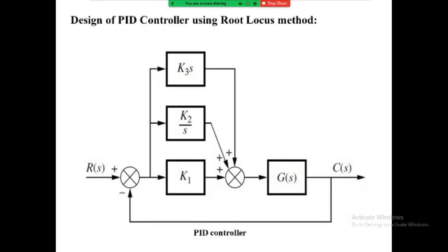In other cases, the improvement in transient response yields further improvement in steady state error. Thus, a system can be overdesigned with respect to steady state error. This is usually not a problem unless it affects the cost or produces other design problems.